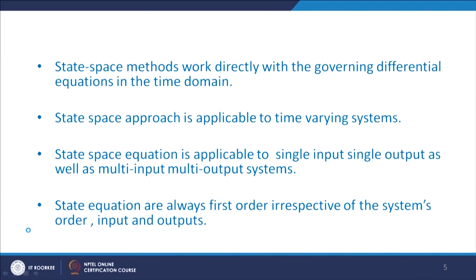The state space approach is applicable to time varying system. You see, the aircraft has some fuel, and it moves up, what happens? Fuel decreases, that again the weight decreases, weight of the aircraft decreases. Therefore, whatever technique you will develop, that should be for time varying system. So that time varying concept can be applicable in case of state space, where it cannot be applicable in case of transfer function approach.